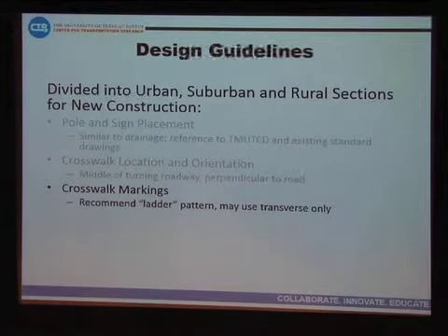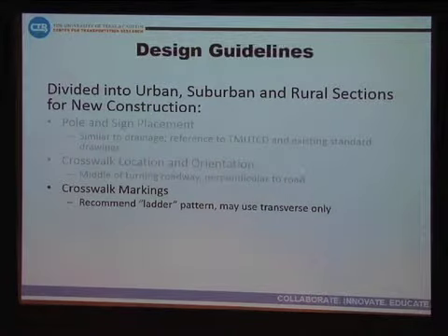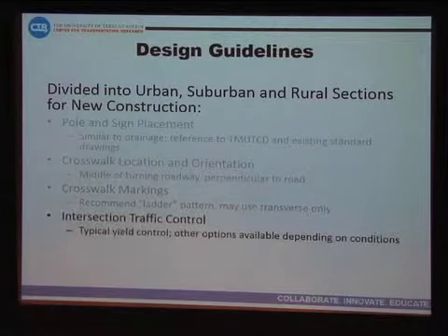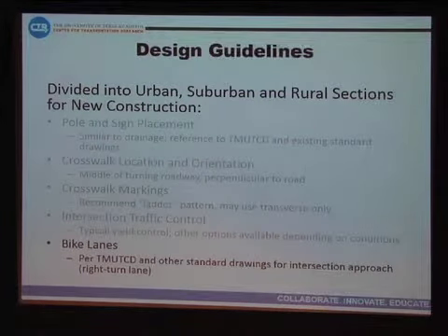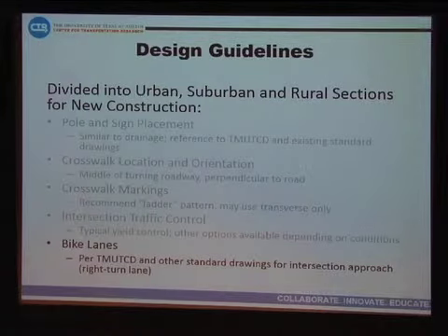With respect to the markings themselves, we recommended using ladder markings, so the combination of transverse and longitudinal striping, while providing the option to use transverse striping only. And for the intersection traffic control and bike lanes, we largely deferred to current guidance provided in the TMUTCD.